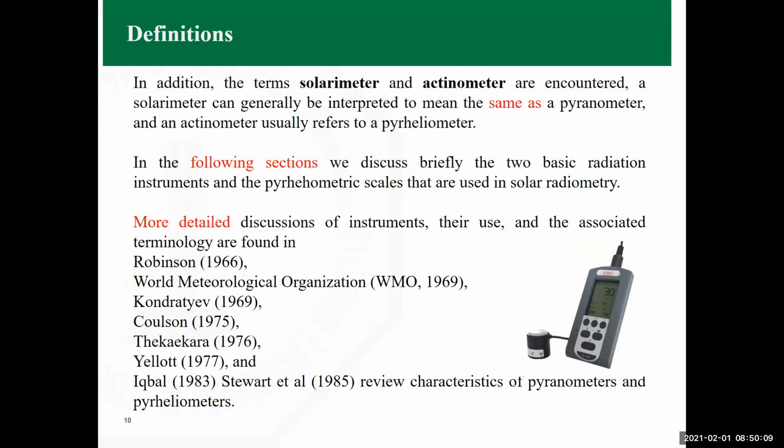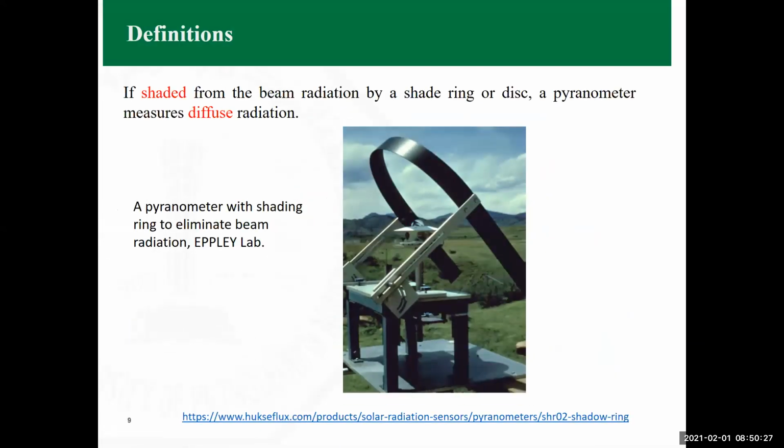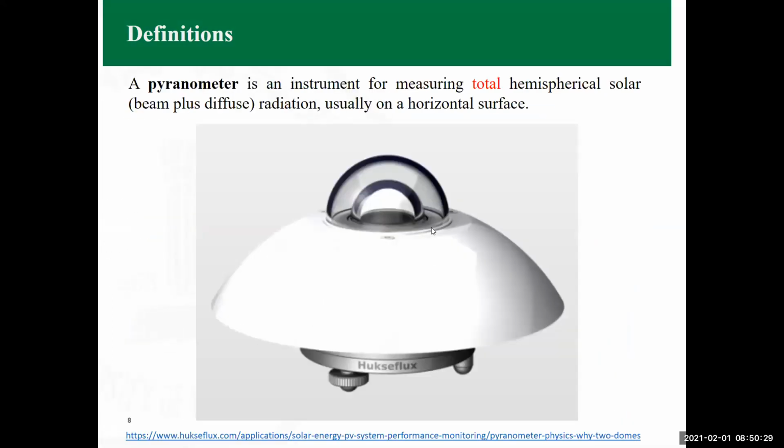If you happen to visit the university and look at the places outside of building 26, you are going to find something like this, which is connected to a readout, and the readout measures the watt per meter square directly, which is the total radiation falling onto the surface. You can also find it in one of the devices that we have here, so that you can use it to measure how much total thermal radiation is falling onto a surface.